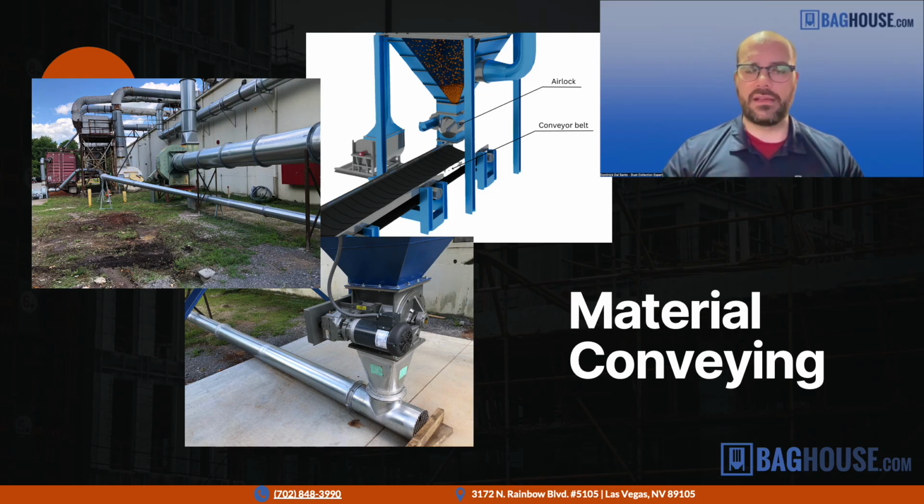Now, when you have pneumatic conveying, you're taking material and you're blowing it or pulling it through basically a small piece of ductwork. We usually call it piping to another space. So in these systems, like we said with filling the silos, for example, you might blow material from your truck that comes with material to deliver, blowing it up into the silo. That's pneumatic conveying. Or you might, from the silo, have it go down and load the truck or a barge or a train car. In that case, you're also doing material conveying, pneumatic conveying.